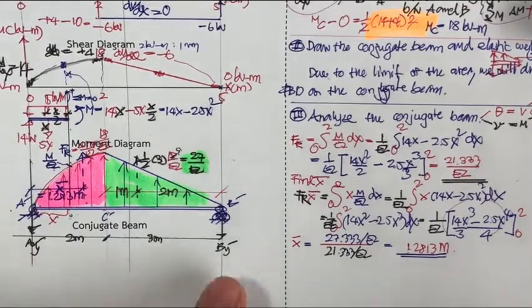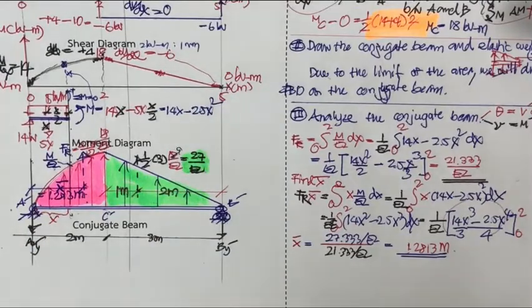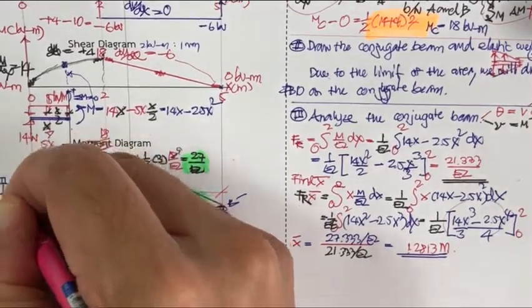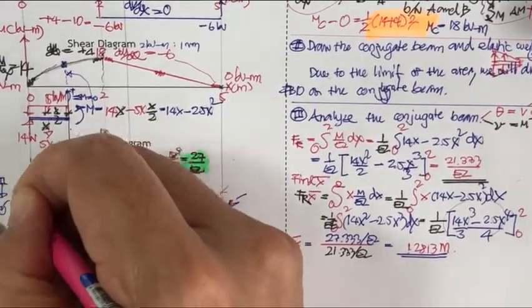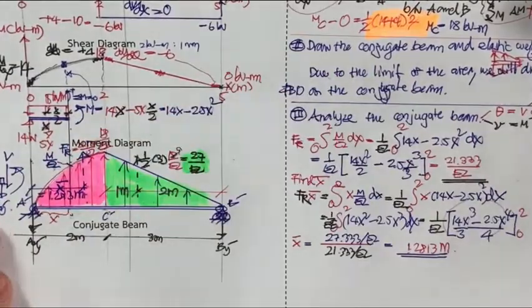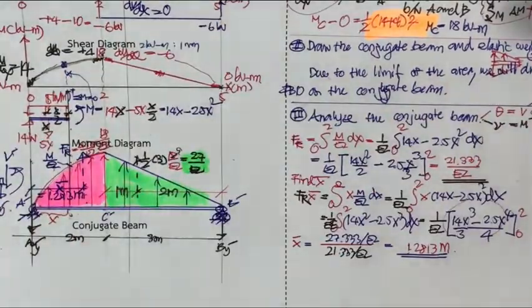Now you are ready to do the calculation for the A sub y prime and B sub y prime, and you may notice that the A sub y prime is also equivalent to the shear. For example, if you cut the beam here, you get the A sub y prime here. You take the convention of the V here going to be in the opposite direction of A sub y prime.